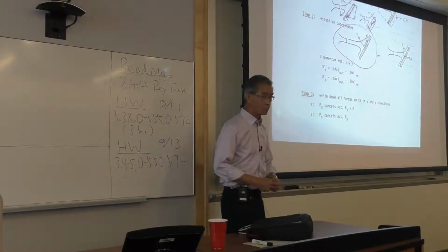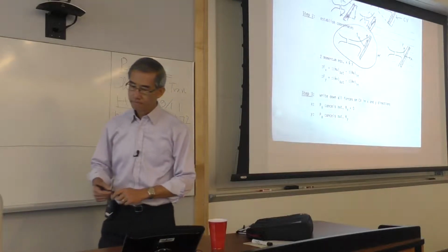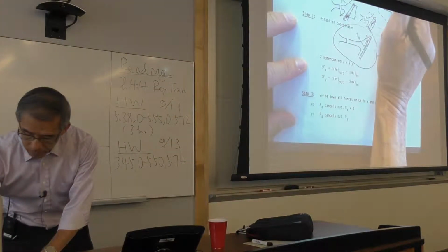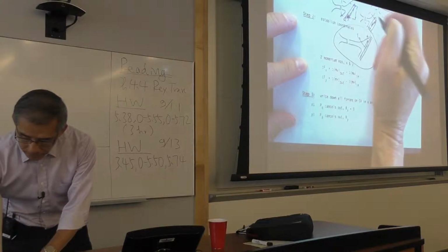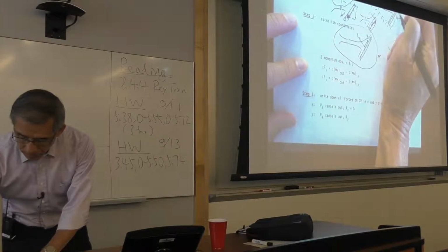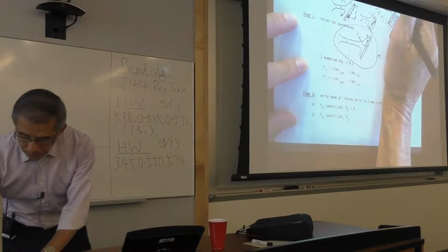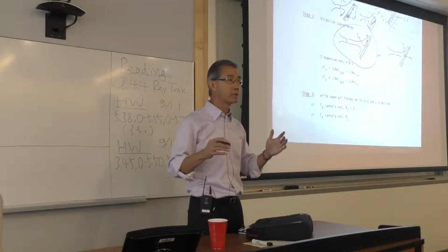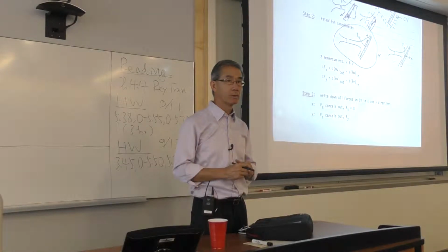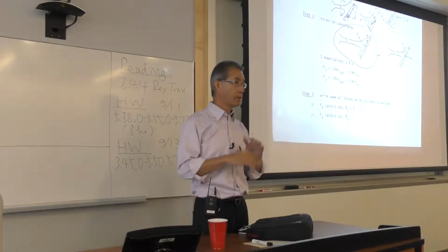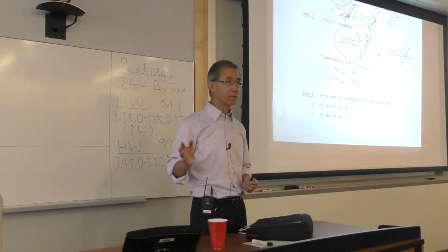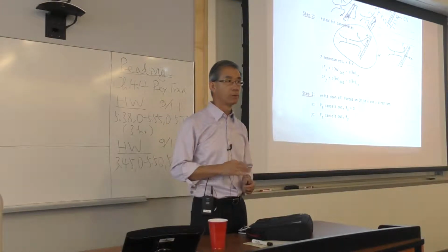So knowing which control volume we choose, which is now this one, I draw all the pressure around them. This is now, for the first time, not a rectangular or white cylinder control volume. It's almost arbitrary shape. But everywhere is P atmosphere. What's the net pressure force both in x and y direction? Zero. Do you get it?